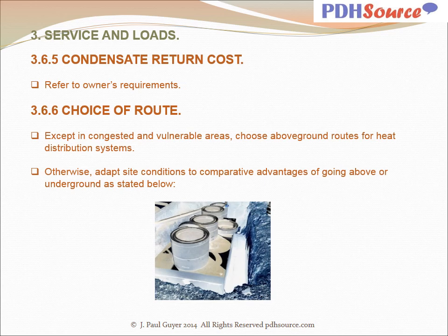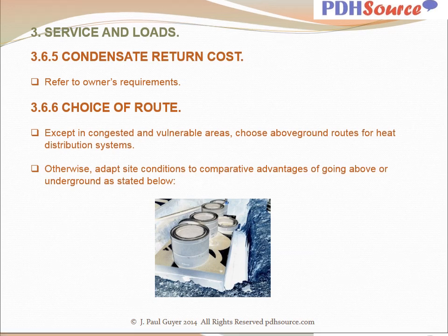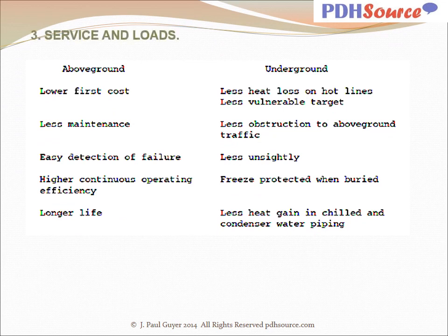Except in congested and vulnerable areas, choose above-ground routes for heat distribution systems. Otherwise, adapt site conditions to comparative advantages of going above or underground as stated below. Slide 36 provides these recommendations.